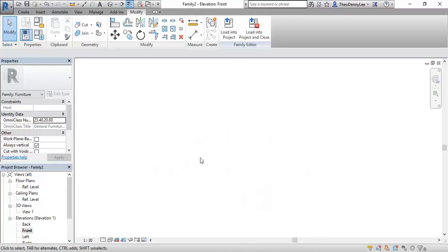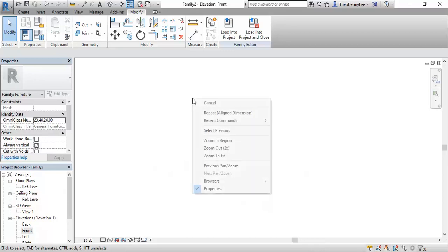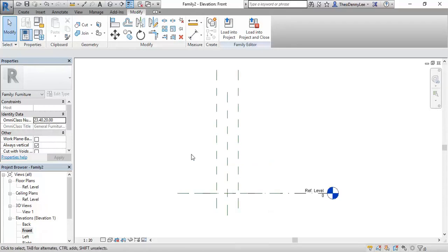So now I can go to an elevation view. Remember what you need to do if it's blank. The guide saved the template, but forgot to zoom in all the views before they set the template off. So you just need to remember, sometimes when you see this, zoom to fit straight away, and that fixes it.